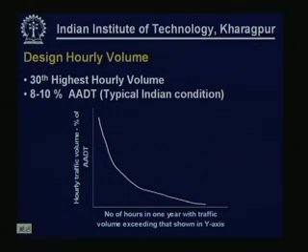We talked about the annual average daily traffic, ADT, average daily traffic, and then converting the same to annual average daily traffic. But normally, not always, the road capacity is defined in terms of the number of vehicles or passenger car units the road can handle per hour. So, it is expressed normally in terms of PCU or PCE per hour.